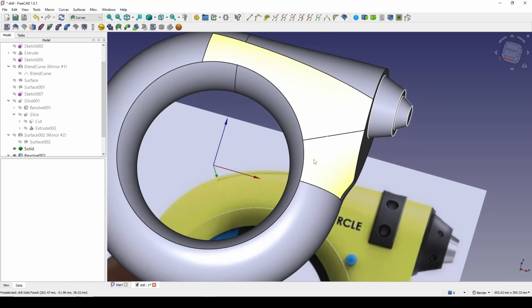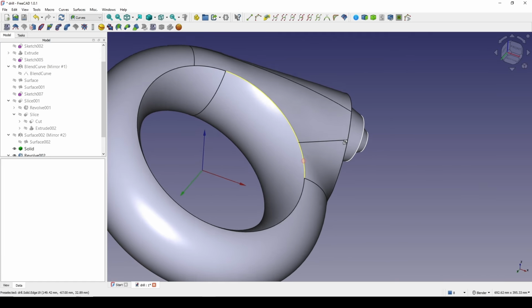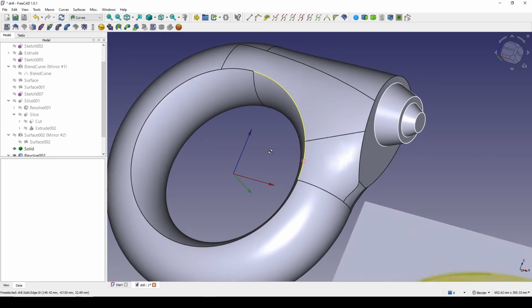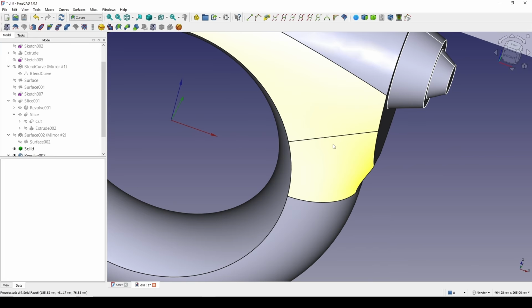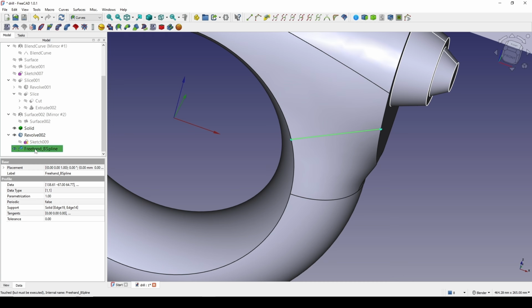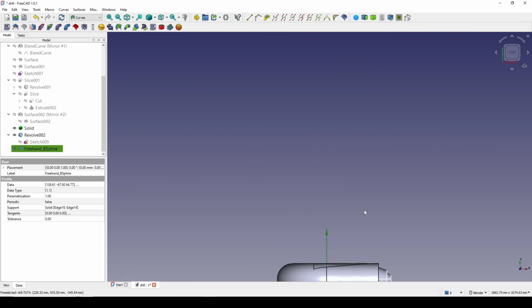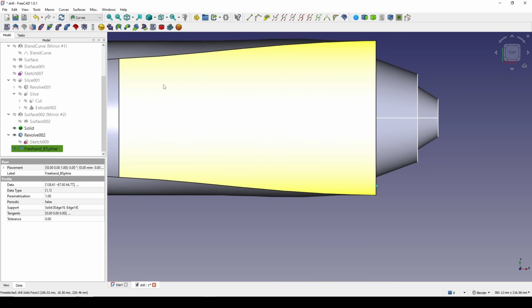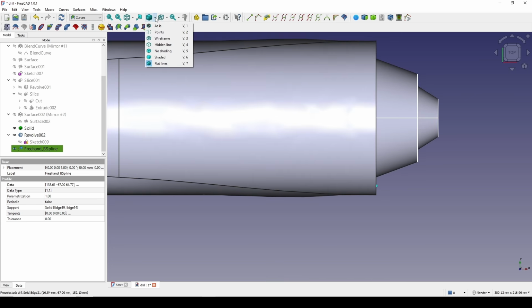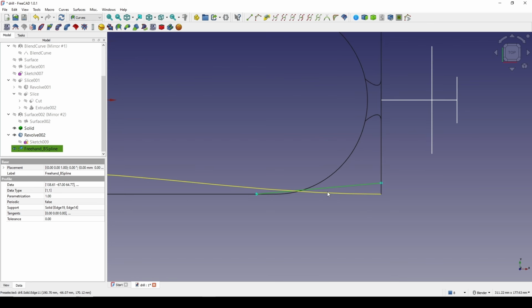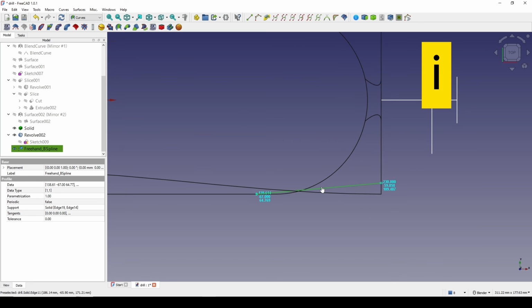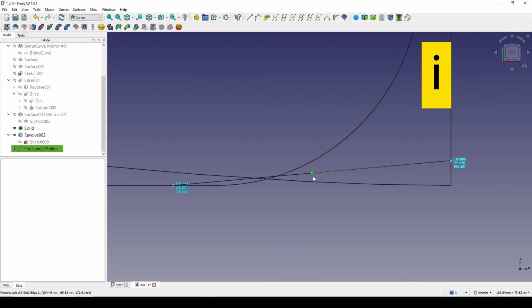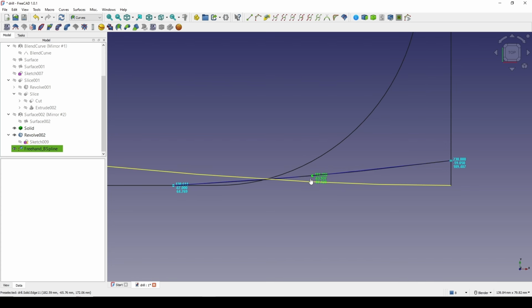Now we just update the surface a little bit, and we can also change the shape of the freehand B-spline by going back here, double click on the freehand B-spline, go to the top view, go to the wireframe, click and hold on the freehand B-spline, hit I to insert a new point, select this point and move this one to about here, and do not go too much.